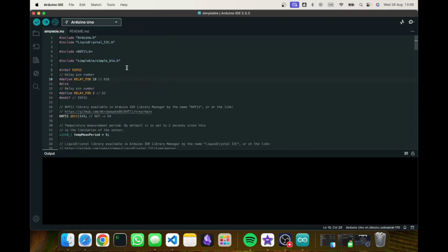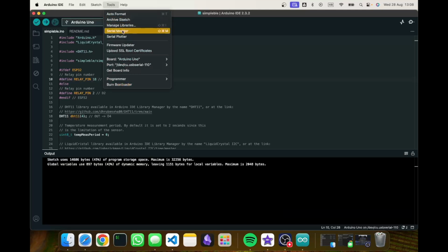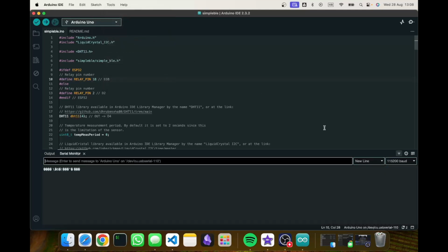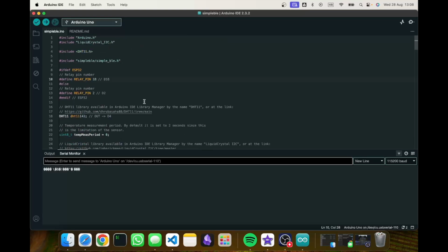Now you can flash this firmware to the development kit. So just press the upload. It should compile with no problem and get uploaded. And that's it. You can also check with the tools here, serial monitor. The board should be this one. It won't start for me because I don't have the sensors connected, but if you connect the sensor correctly, it should start the example. It should write example started, and yeah, move on.